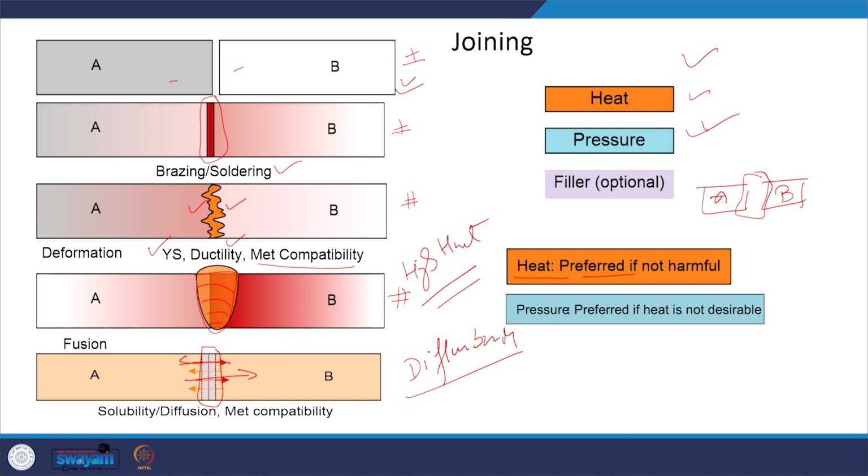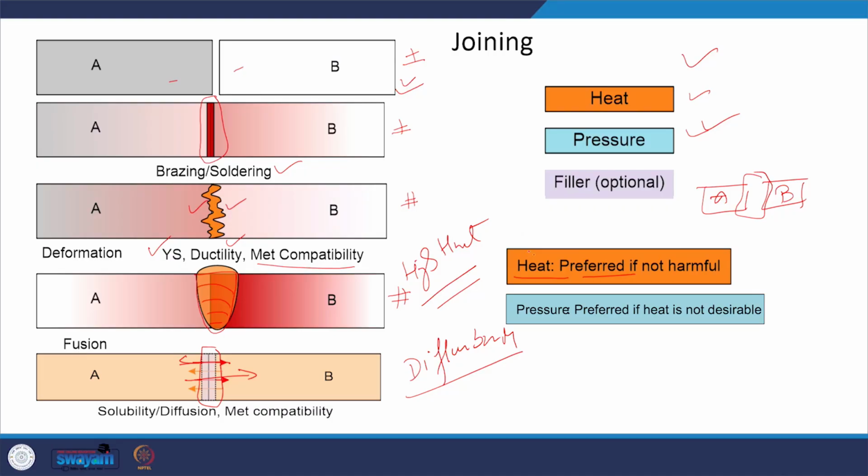Many times the degradation in properties is so huge that in those cases, the application of heat for development of the joint is not really a good idea. So, in that case, pressure based weldings or deformation based processes are used. So, heat is used if it is not harmful, and pressure is preferred if heat is not desirable. Sometimes we use a combination of heat and pressure both in order to facilitate the joining of difficult to weld metals.